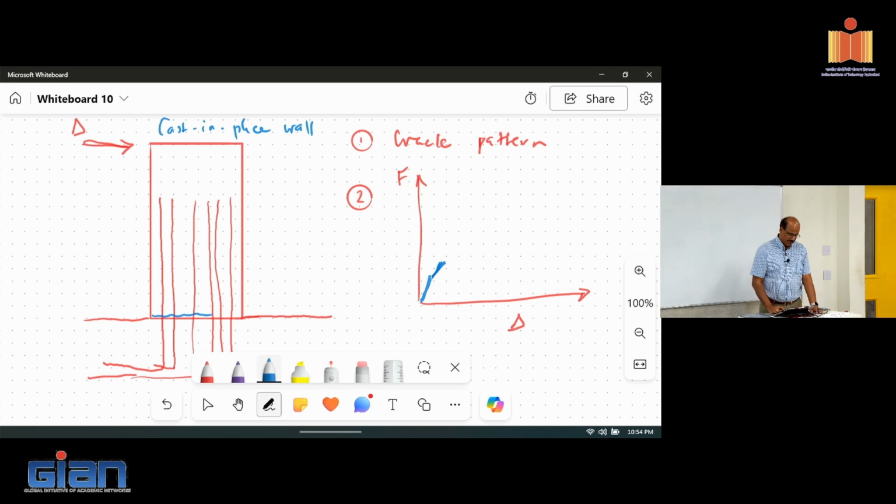As you keep pushing it, you're going to start seeing more and more cracks developing, right? Why do you think we develop more cracks? Every time you exceed the flexural tensile strength at that section, the rebar doesn't get engaged until the crack develops. You design reinforced concrete with the reinforcement basically to take the tension. They won't participate actively until the crack develops.